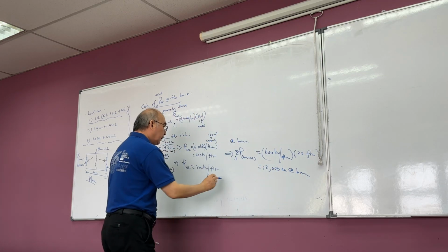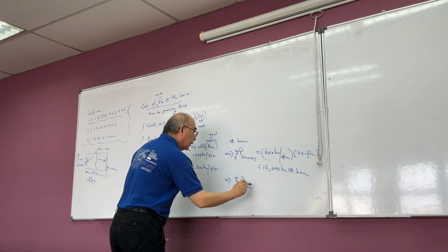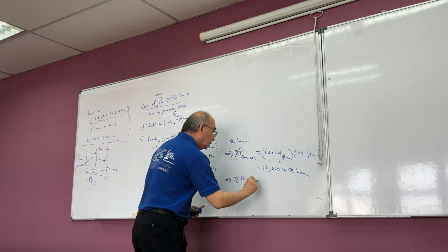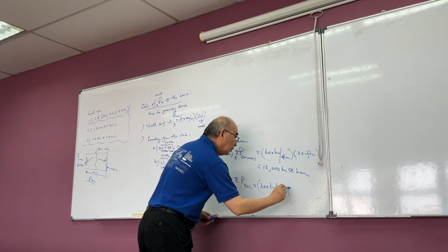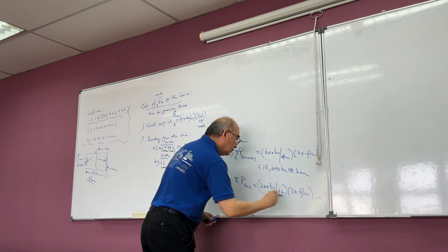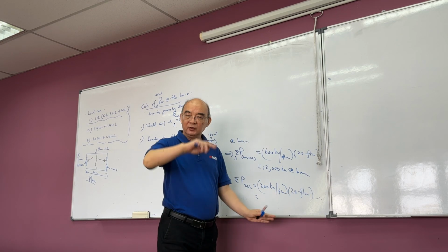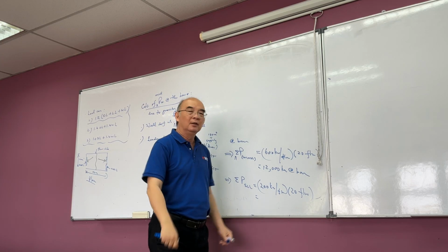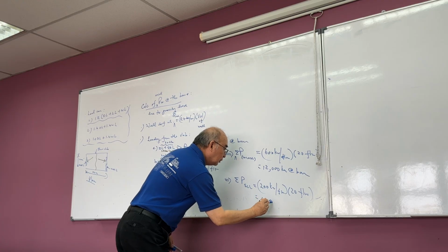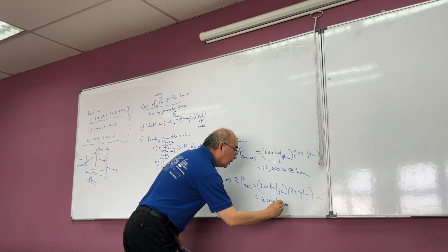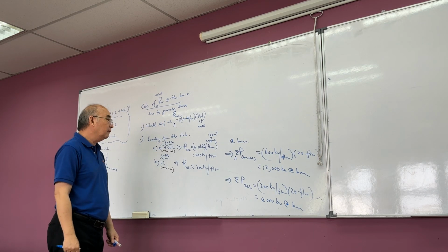Then the same thing. Summation of PSLL is equal to 200 kilonewton per floor multiplied by 20 floors. But this could be 30 floors, 15 floors, 10 floors, so you have to look at that. Then this should be 4,000 kilonewton at base.